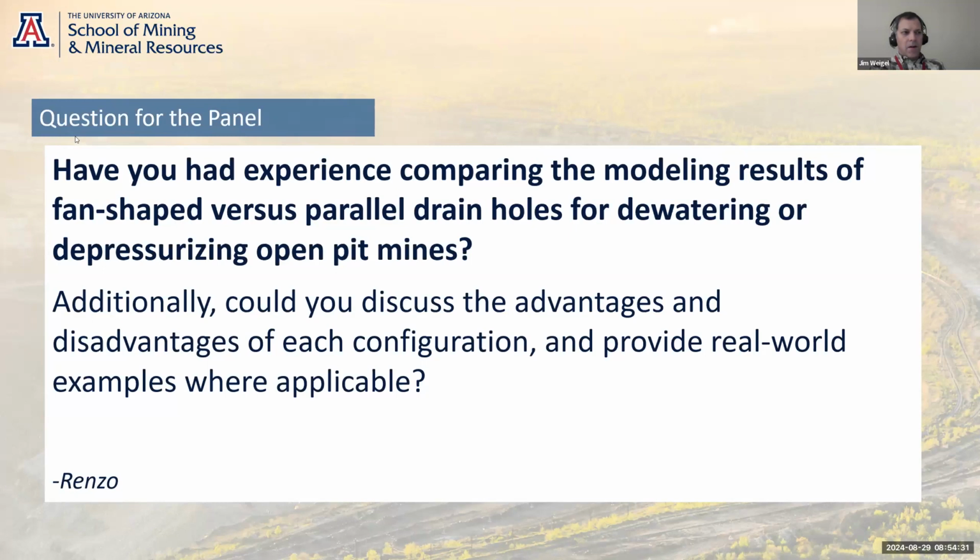For us, we use it as an insurance policy as much as anything else. While we do put fan drains in our models, a lot of what we do is more physical based in what we're seeing. We do try and get additional piezometers in so we can demonstrate the depressurization. It's one of our insurance policies with our very large walls, to have that horizontal drain drill rig in place.